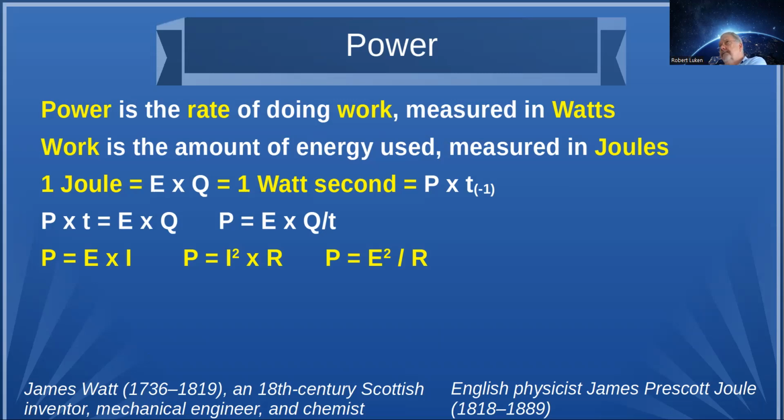What that means is, if you took an infinitely long piece of coax and put an ohm meter across it, it's going to look like 50 ohms. Obviously, you're not going to have an infinitely long piece, but that's how the characteristic impedance is developed,